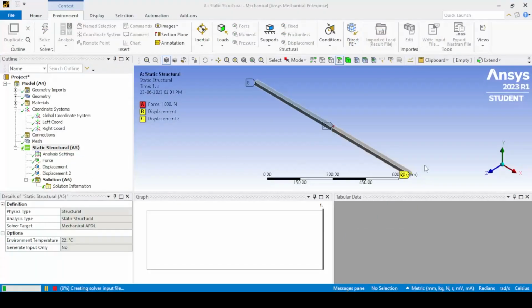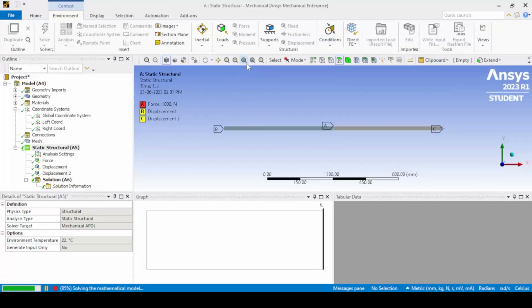Note that applying the fixed support is the wrong approach, since a simply supported beam means the vertical movement is 0, but the slope is not 0. Therefore, the fixed support violates the condition. This is the accurate approach that comes from the theory.